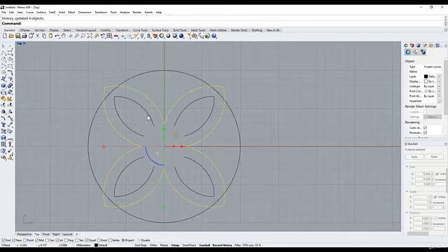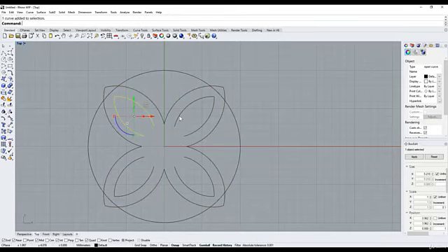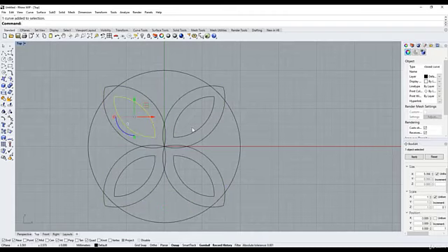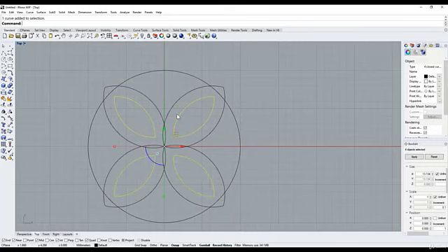And you can see that our child objects here are now updating because our parents were trimmed. So you can see our children there, we want to maintain what they were like. So I'll Control Z, and I'm going to select these 4 items here, and I want to break their history. I want to remove that relationship, stop them from being child objects.